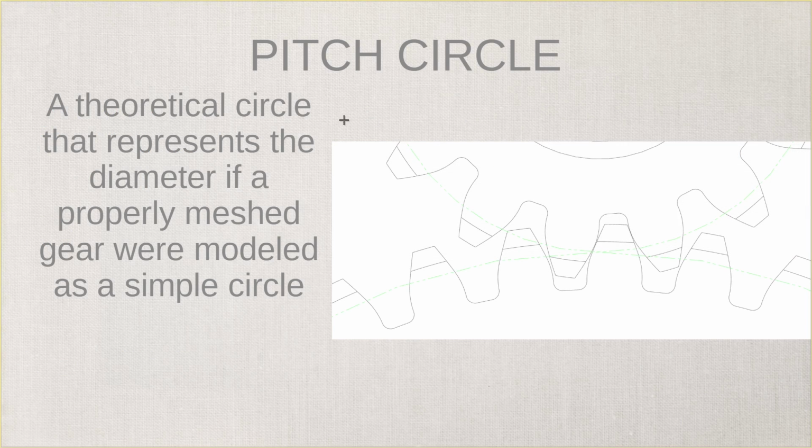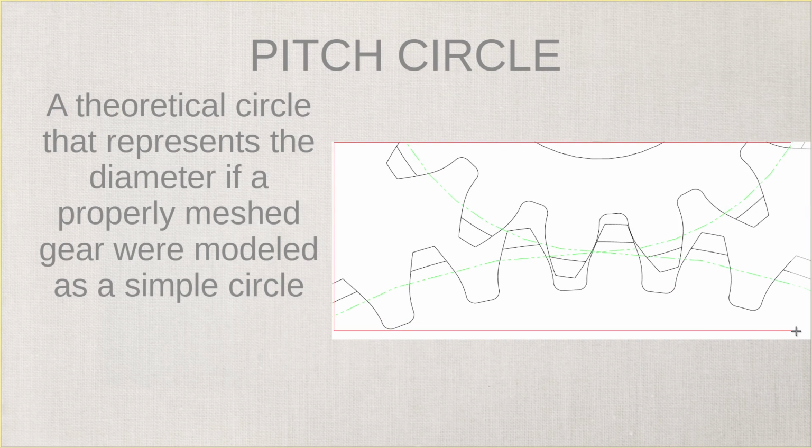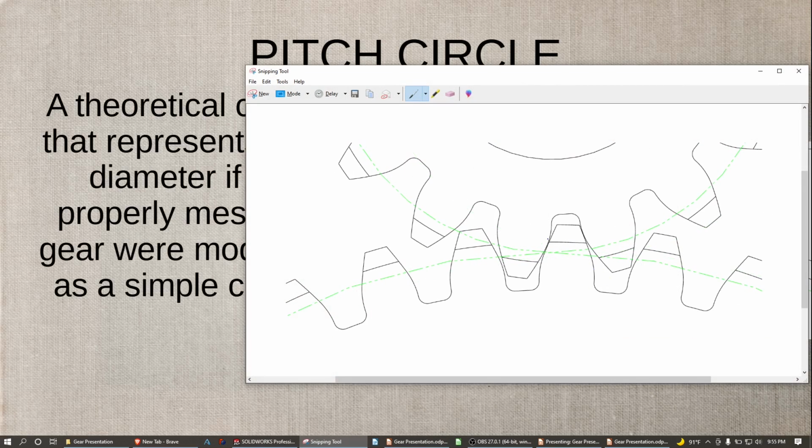I did not talk about pressure angle very much, so let me just grab this real quick so I can draw this out. You have two curved surfaces on this gear pushing on each other, and so the force is not going to go this way. No good. How the force actually goes from tooth to tooth is at an angle. It will head about this way.